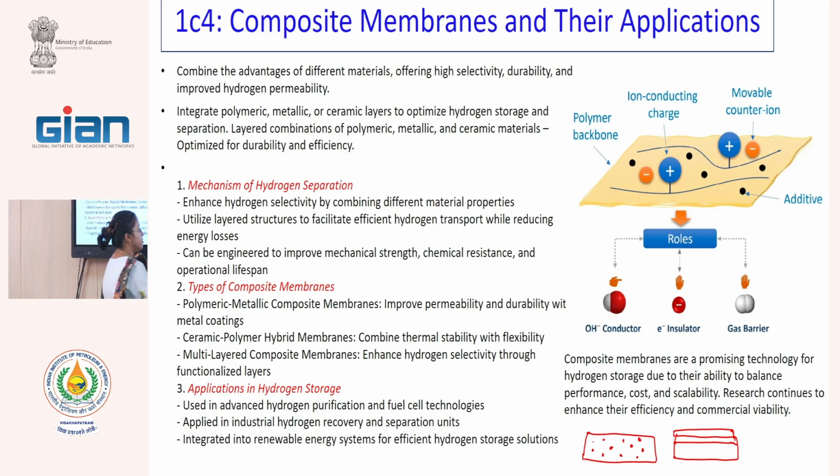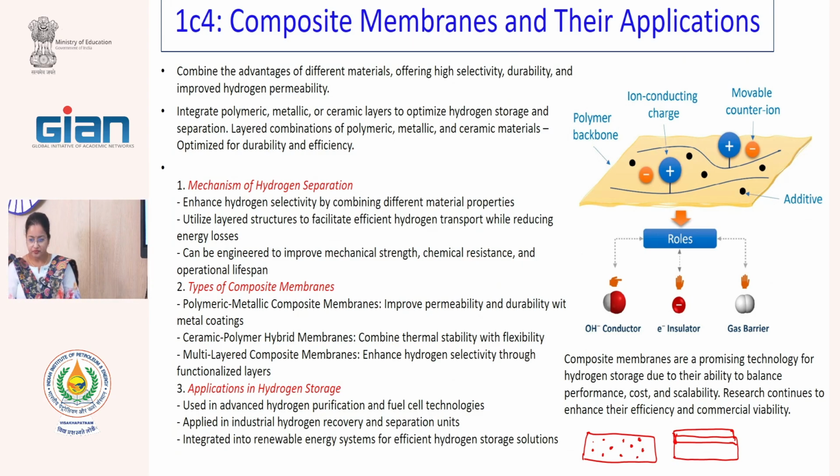So, one thing we have to be very sure about when we are using any kind of operation like this, is that the membrane materials are not leaching out from the membrane. Whenever we have any composite, not only for gas purification but also for liquid purification, during the operation process, if the membrane material leaches out from the treatment, then the membrane efficiency goes down. So, while characterizing the membrane, while making a new membrane, we always test the stability or whether it is leaching out. Those things are very important.